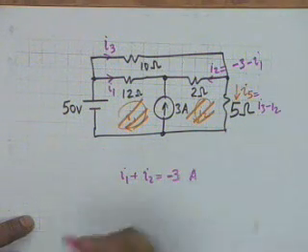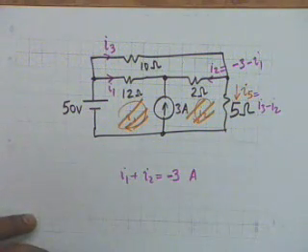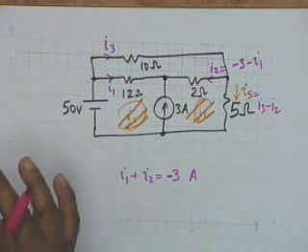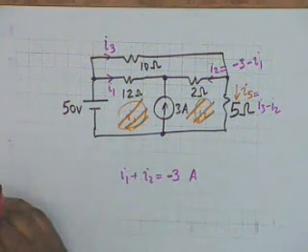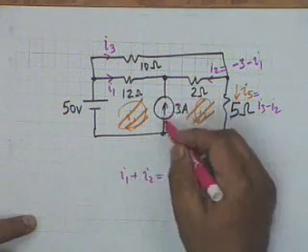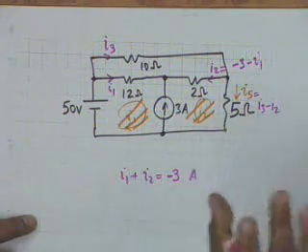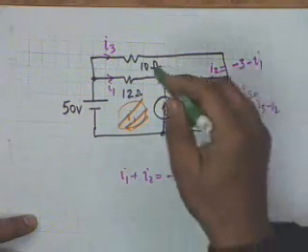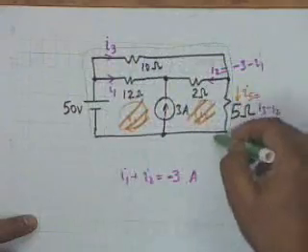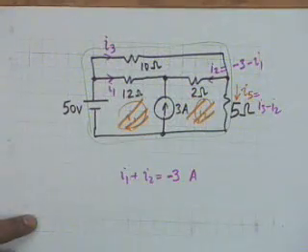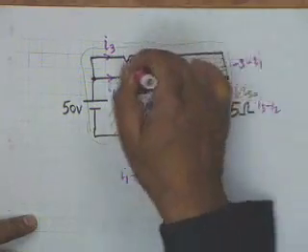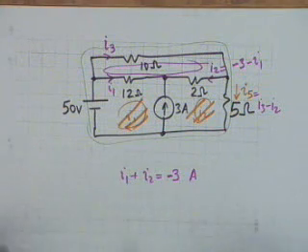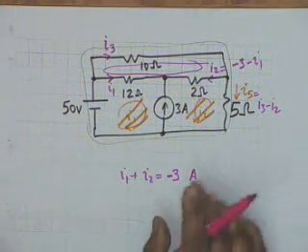Alright? And therefore, how many currents are unknown? Only 2. And it suffices to write 2 loop equations. Now, carefully avoiding the current generator. The current generator must not be inside a loop. So, what is the choice? The bigger loop. Well, you can go like this. This is one loop, and the other one is the upper loop. Okay, 2 loops which do not contain a current generator. That is enough, because there are only 2 unknown currents.